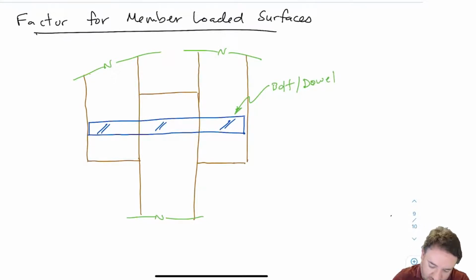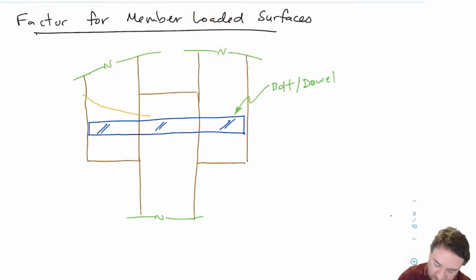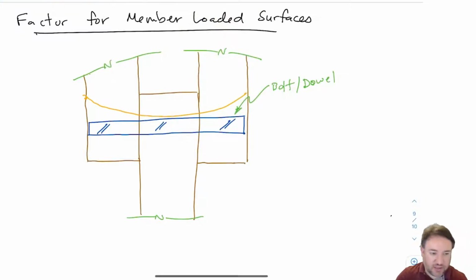So when this bends, you can imagine, we're going to get some bolt bending shape. At the end of the bolt, we're basically not going to have that much load because the bolt is flexible. So when it's bending, at the end, I'm going to get less and less stress as I get toward the end of the bolt.